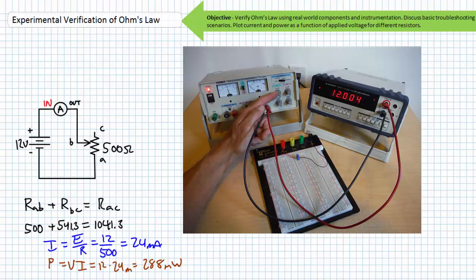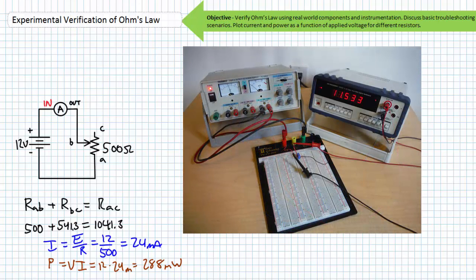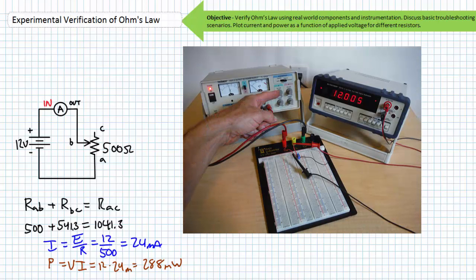With our 500 ohm resistor attached to our power supply, our DMM in voltmeter mode shows the output voltage drops to around 11.5 volts. Again, keeping the DMM in voltmeter mode, I can readjust our output power supply back up to the 12 volts we require when in loaded conditions.